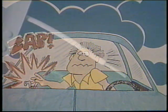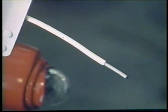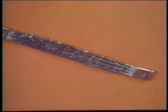Static electricity must build up to a voltage high enough to pass off through one of the three neutralization methods. Large and smooth control surfaces will store huge quantities of electrons, so static dischargers having sharp points may be used to dissipate the charge into the air before it can cause radio interference. Flexible, conductive bonding braids connect control surfaces with the main structure to neutralize the static charge that builds up as air flows over the surface.